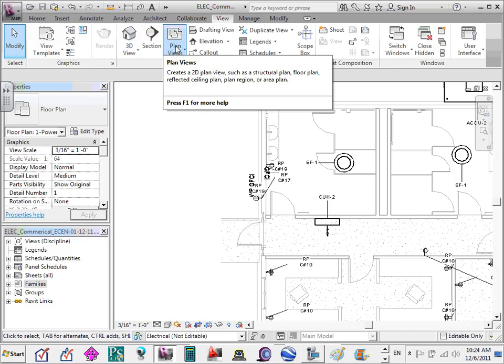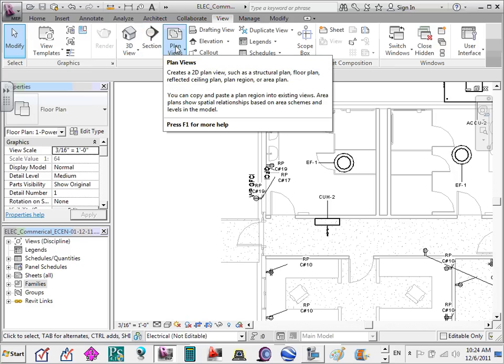The other thing under drafting that we used a lot last time is sections and plan view. If I want to have a section, cut this building by half and look at it this way, they are very powerful. For example, when you drop your fixture, it looks like it's sitting good. You do a section and you look at it and it's attached to the floor. That's when we start checking your work, circuit, everything is good. You'll be surprised, because this is a new system for all of us, a lot of fixtures were actually attached to the floor. So what do we need to do then? We need to offset them off the floor all the way to the ceiling.